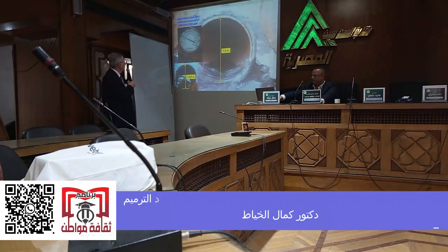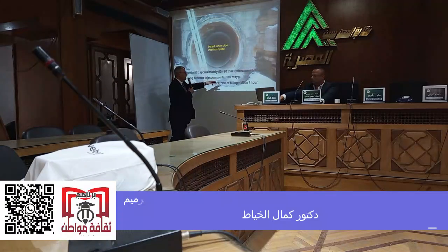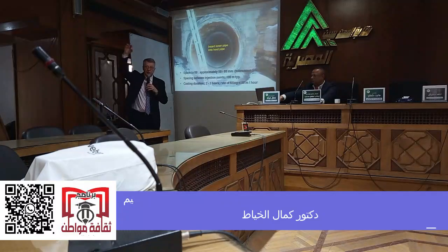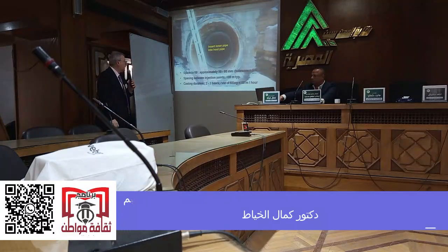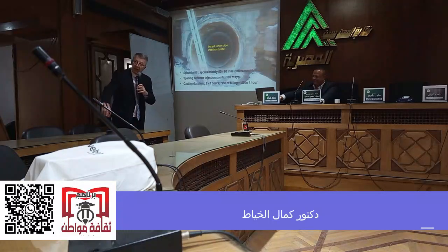And you have to inject that. So water pipes are at 150 psi. And again, if there's any corrosion blow up, you basically have a geyser from the city street. Next, please. So the space that needs to be filled varies between 50 to 80 millimeter. And the spacing between the injection points are the maintenance holes on the street level, and they are usually spaced about 100 meters. So you have to go from one maintenance hole on the city street all the way to the next, all the way 100 meters.